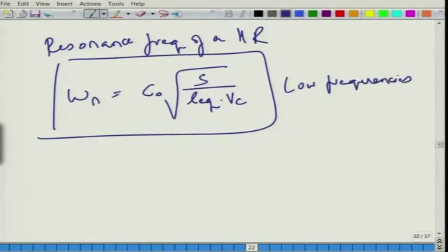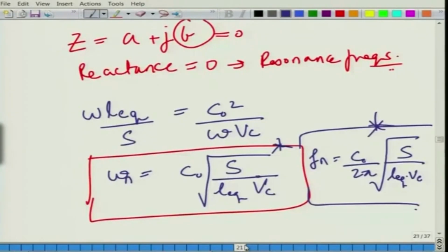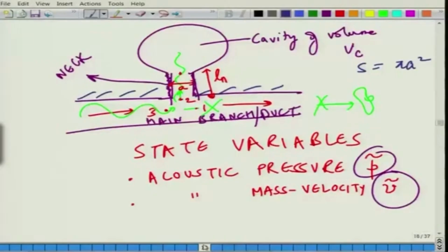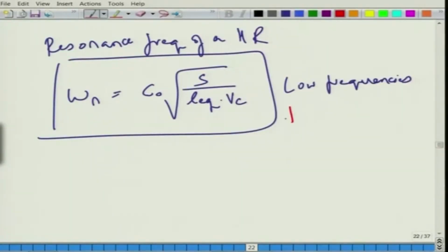So, how do you determine if the frequency is low or not? This is actually a matter of analysis for the later parts of the course, but I just want to mention here that every cavity has some resonance frequency. So, one can do a 3D finite element analysis, get an algebraic eigenvalue problem for this and get the resonance frequencies for this one, and for this pipe we know. So, whatever value we are getting using this equation, let us say star, that should be less than the resonance frequencies of the cavity at least. So, then we can be confident.